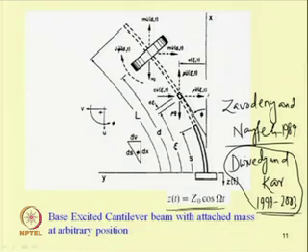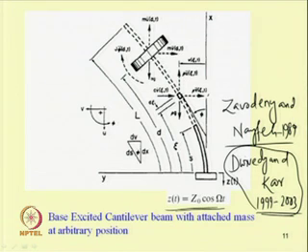But as we are interested to study the internal resonance case, by varying the mass position, one can show that the system has many different types of resonance condition. For example, one can have this internal resonance condition of 1:3, 1:3:5 and 1:3:9. So, these are 2 mode interaction and these two are 3 mode interaction.